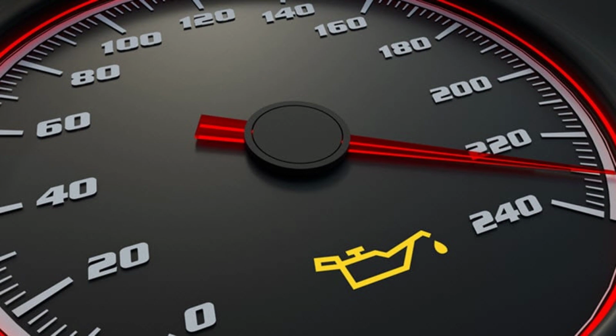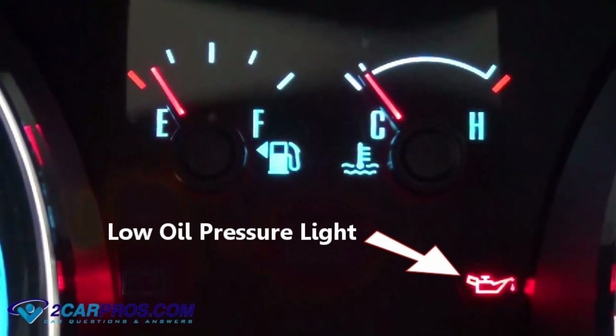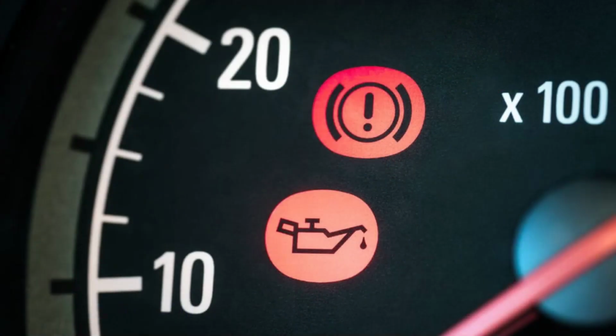The P0522 code can manifest in a variety of ways, depending on the severity of the issue. Some common symptoms include illuminated check engine light. This is the most common symptom, indicating that the engine control unit, ECU, has detected a problem with the oil pressure sensor circuit. Low oil pressure warning light. This light may illuminate if the oil pressure drops below a safe level. Engine performance issues. The engine may run rough, hesitate, or stall if the oil pressure is too low. Unusual noises. Tapping or knocking noises from the engine may indicate low oil pressure. Oil leaks. Leaks can cause the oil pressure to drop, triggering the P0522 code.